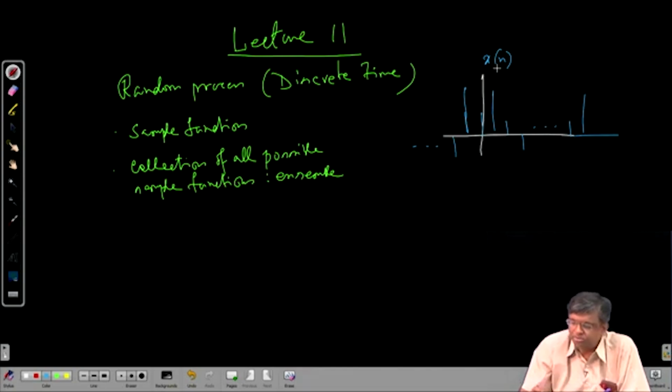Okay. Now, here every sample is a random variable, because if you consider this to be the nth index, this point, next time when I observe another sample function, I am sure you will not see the same value, its value will change. It can be complex or real, but its value will change, because every sample at every point is a random variable, randomly fluctuating. That means if I restrict myself to a particular index n, the nth point, remain there and keep observing the sample value as I go on doing the experiment, observing various sample functions one after another, I will see different scalar values for this sample. So, this sample located at the nth point will itself be a random variable, right.